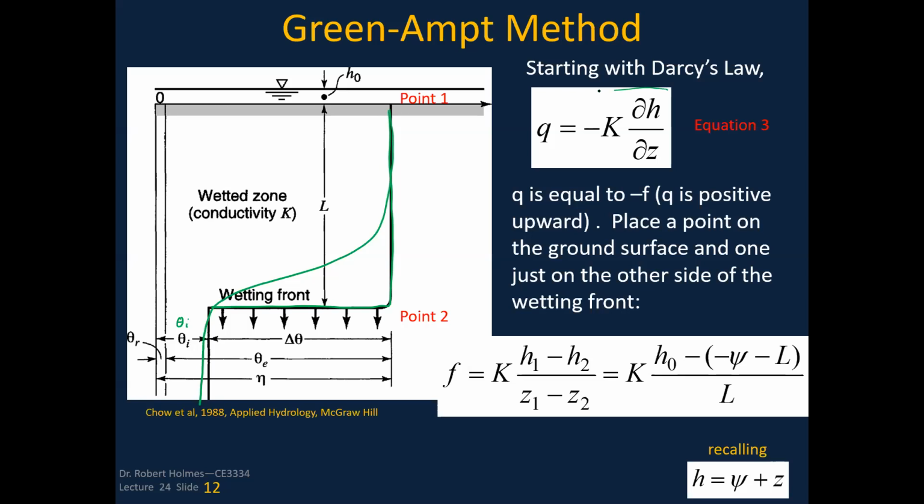And again, we go back to this Darcy's law here, and we've got this value. If we look at the total saturated value of the soil, that's going to be the porosity value. And if we look at this, we can say that this Darcy flux is analogous to the infiltration rate, right? Because this has units of length per time. Infiltration rate has length per time as units.